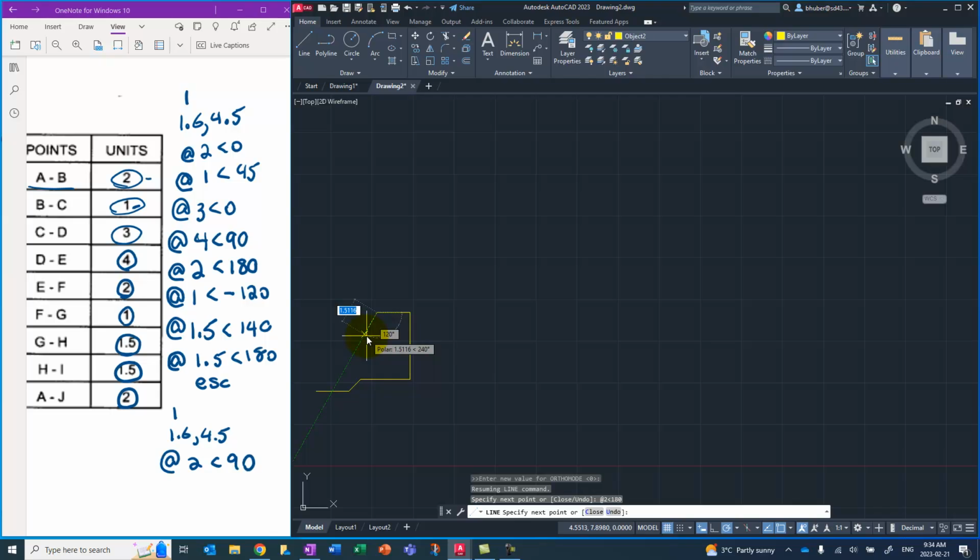So you just got to watch if you are using the dynamic input here. See, I wrote down negative 120 for this move. But one thing I've noticed about the dynamic input is as you drag the cursor around, it's calling this positive 120, and as I slide around, it's calling this positive 120 as well. So if I type this as a negative, well, why don't I show you? If I put 1 as my distance, and then press tab and go negative 120, it basically gives me the reverse of what I wanted.